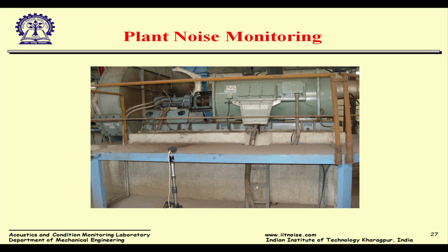And of course, they wanted a permanent solution, so we worked on an enclosure. If you put an enclosure, it leads to another engineering problem. I may reduce the noise, but I may screw up the thermal system, in that the temperature may increase and the bearings may be exposed to high temperature, and that leads to another problem. So there are actually chillers in the intake and exhaust silencers for those enclosures as well, to cool the air.